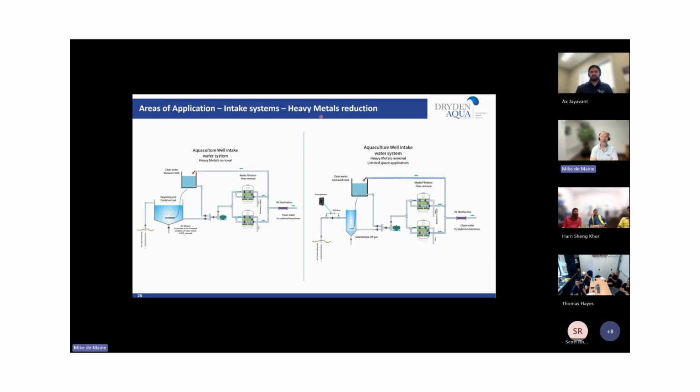So generally for seawater intake systems, I always recommend this because of the variability of the loads. So either during storm surges or during algal events, you might have high TSS loads greater than 20 milligrams per liter, right? So in those situations, I always recommend putting a thin layer of anthracite, not activated carbon, anthracite, on top of the AFM, because what the anthracite then does is it acts as a pre-filtration for the larger particles on top of the AFM, because if those larger particles come down into the AFM, they do what's called blinding the surface of the media.